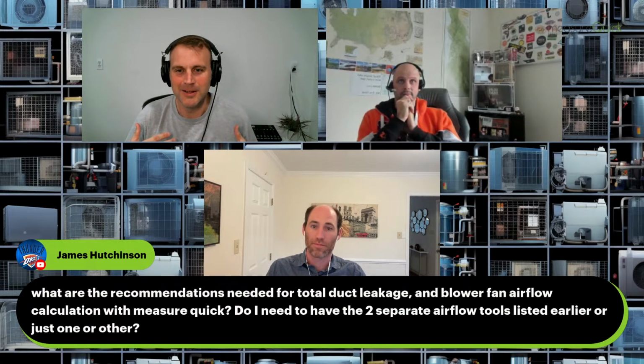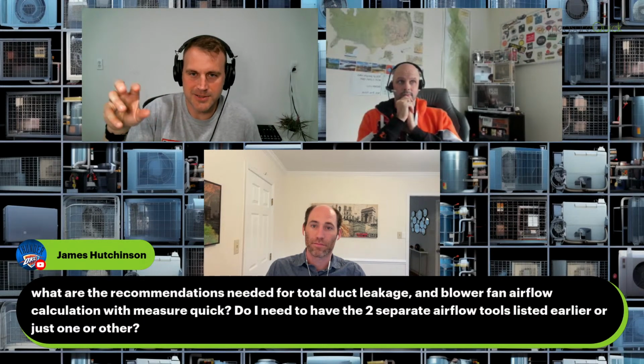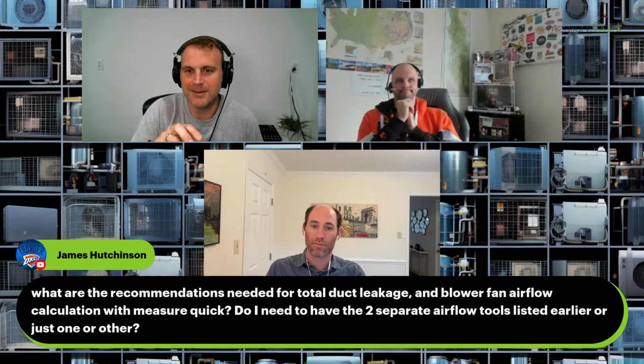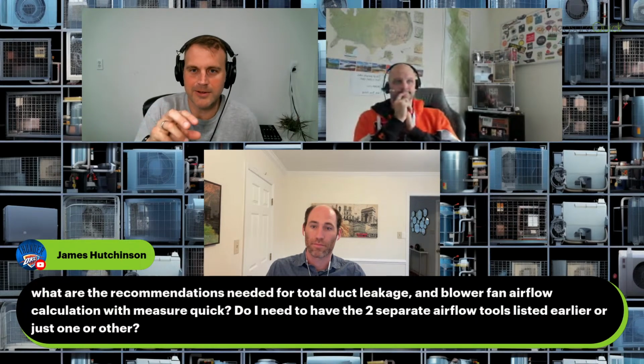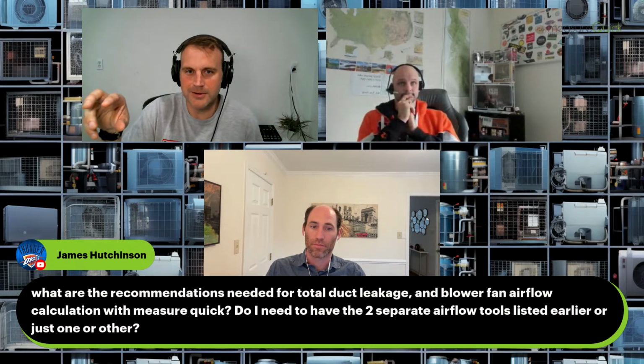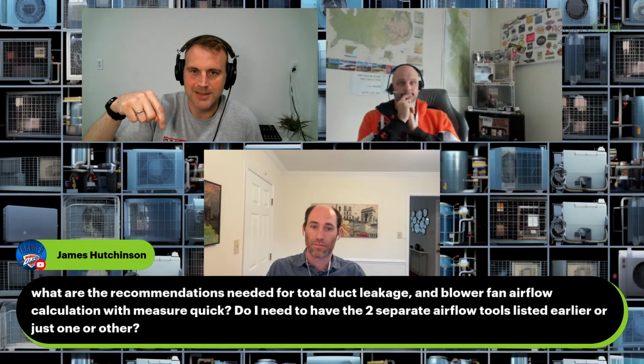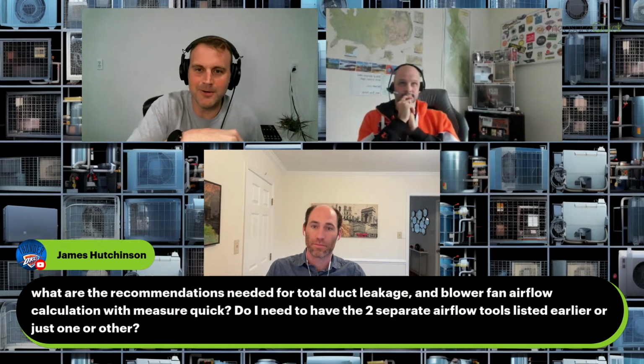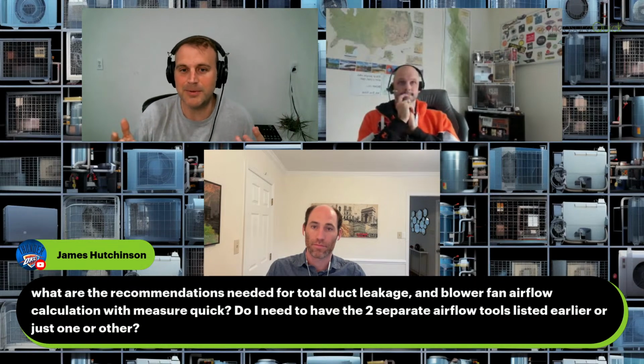So back up to, if you follow the standard 310, and there's a standard 310 tool you can follow, if you have a significant amount of duct leakage, it'll basically say you're not passing, right? And a lot of people I've talked to, they won't even continue. They'll just go back to the builder and say, hey, you need to address this duct leakage, and I'll come back when you do, and then we'll keep going. And that's how the game should be played.